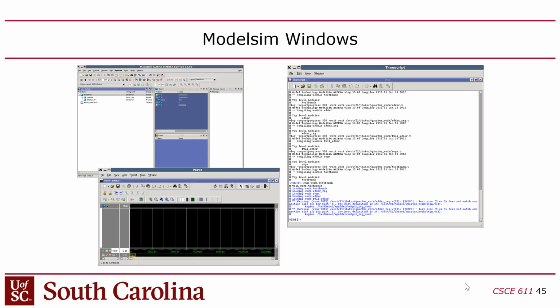Okay, so once you simulate it, it'll reconfigure the GUI a little bit, and you'll see different things in here. There's a waveform window, and then there's this objects window. One thing I want to point out is that over here on the left panel, there is a tree. This thing is cool. This is the design hierarchy. You see it here in this tree structure. So you can drill down into whatever module you want by clicking into this hierarchy.